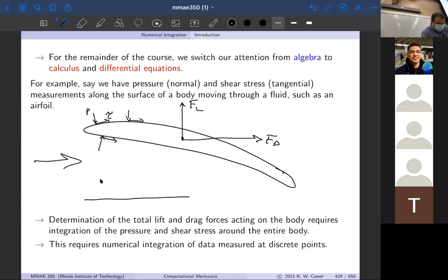So if I have a surface and I have a flow past the surface, that creates a shear stress. So what you do is you put a drop of oil on the surface before you turn the wind tunnel on. You know the viscosity, you know the properties of it. When you turn on the wind tunnel, that drop is going to look like this. It's going to take a shape like that.